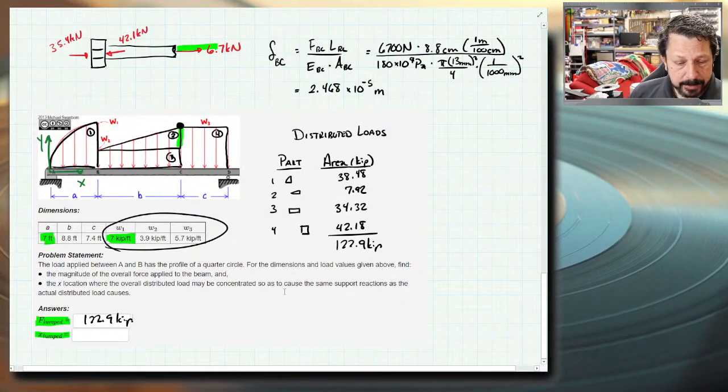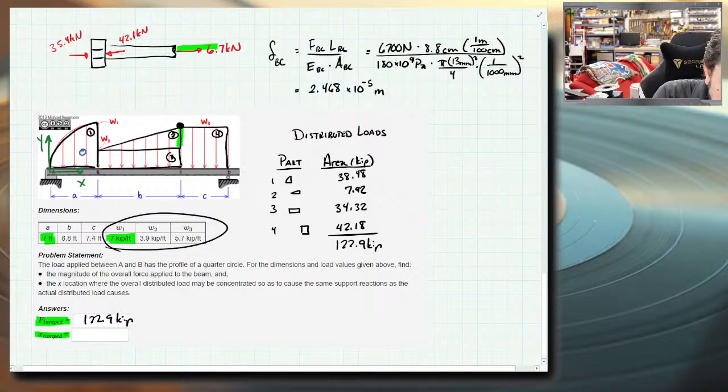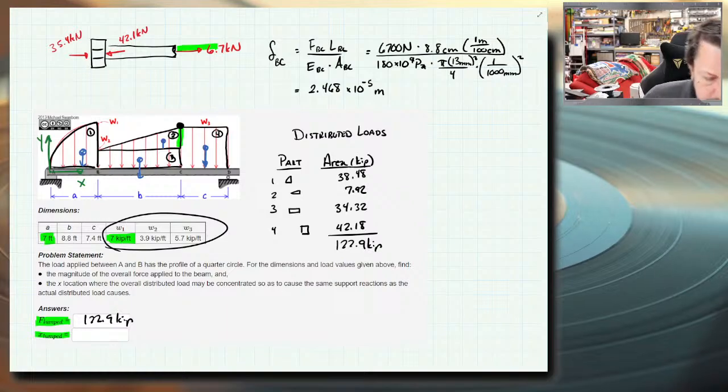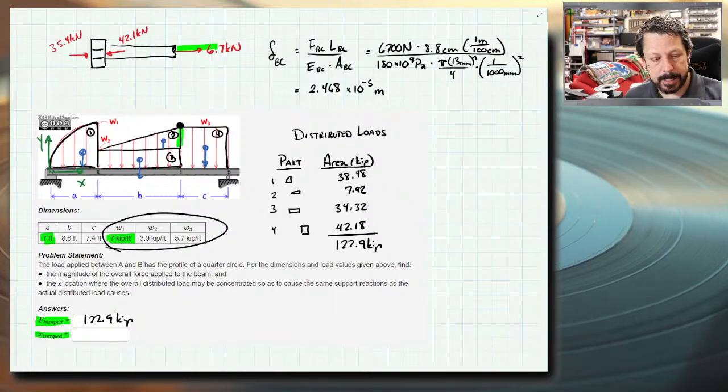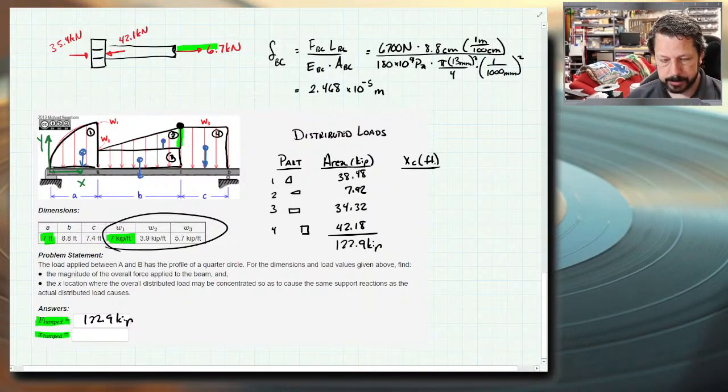Then what I would do is treat these as areas, and maybe in blue, just mark where the centroid of each one would roughly be, just by eye. And measuring from my reference y-axis, I get the x-coordinate, in feet, of each one of these.